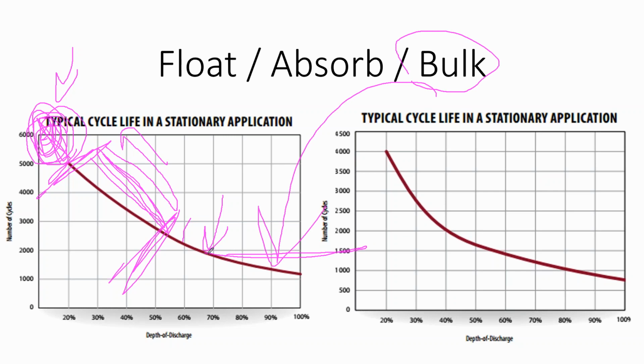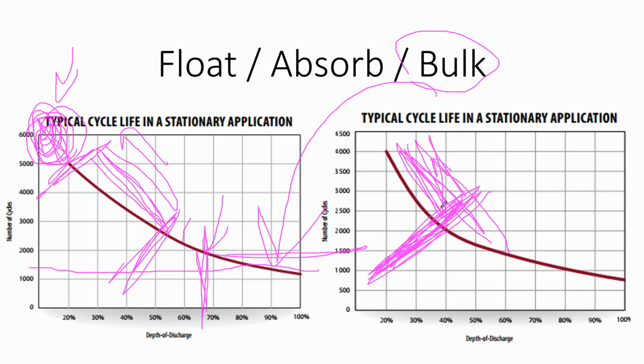And so once you get into this bottom range of depth of discharge, it's not that you can't discharge it, but that adage that if you deep discharge a lead acid battery, it won't charge all the way back up again, they're really talking about if you regularly discharge it below the absorb phase. You want to make sure that your battery is sized so that your day-to-day operation stays above this inflection point. And once those cloudy weather systems come through and your battery starts to discharge down here, you want to crank your generator and charge it all the way back up to the top.